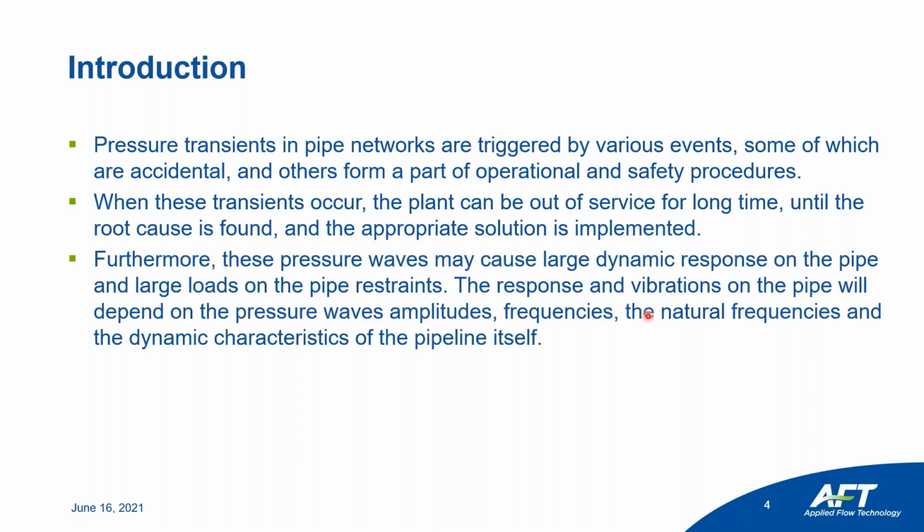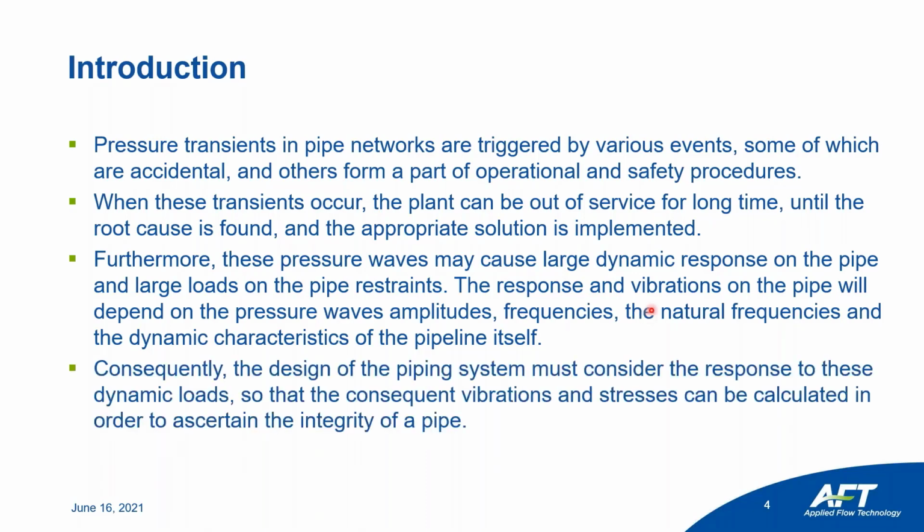Furthermore, these pressure waves may cause large dynamic response on the pipe and large loads on the pipe restraints. The response and vibration on the pipe will depend on the pressure wave amplitude, frequencies, the natural frequencies, and the dynamic characteristic of the pipe itself. Consequently, the design of the piping system must consider the response to these dynamic loads, so the consequent vibration and stresses can be calculated in order to ascertain the integrity of the pipe.